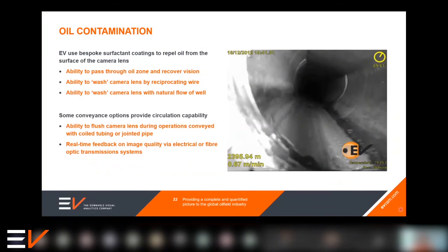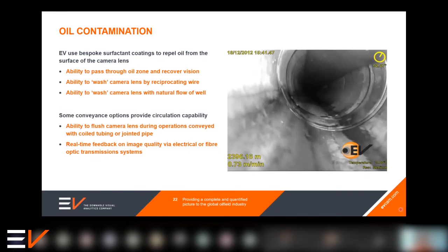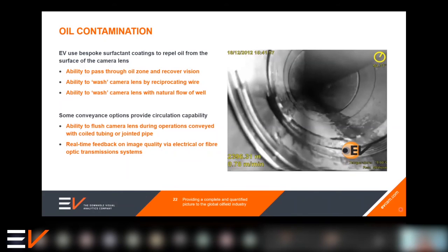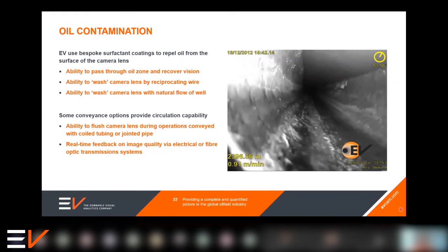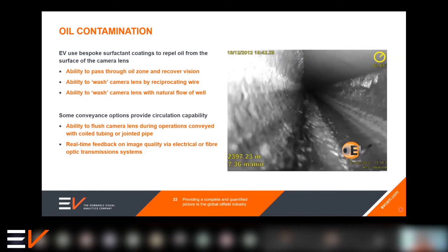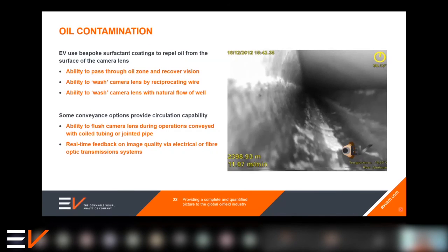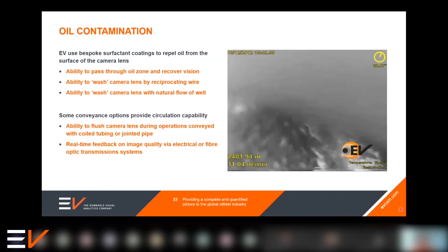As long as we've got some sort of clear medium in there at the area of interest, whether it's a gas cap or a water column, and we could potentially manipulate the height of those with some applied pressure at surface, or we could bullhead, or in this case, you could even rely on the clarity of the produced water or gas. But if there is oil, it's not an issue.